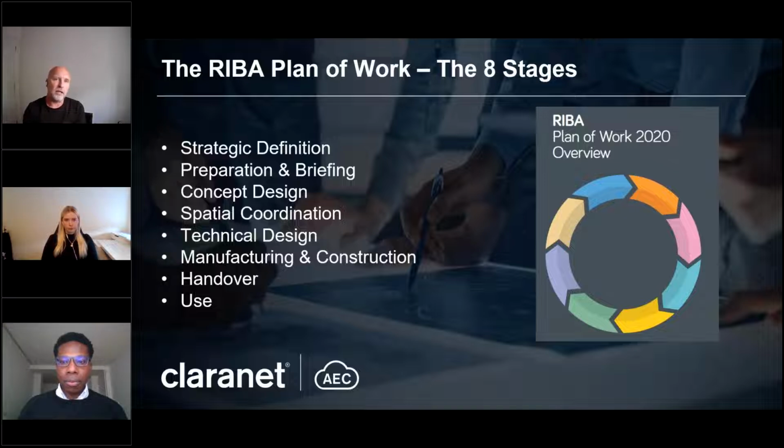And the real underlying outcomes and tasks that come out of these stages are typically things like a business case, the site selection, and planning. How do they apply for planning permission to go forwards with that project? Then you move into the second stage, which is actually stage 1, because stage 0 is strategic definition. You don't necessarily move from there. If the strategic definition defines that the building is not going to be scalable, won't be feasible, isn't viable, it doesn't move to a project.